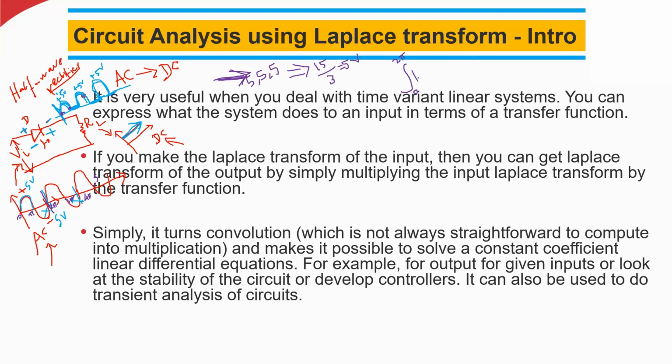So this one is Vm sine omega t dt. Sine is representing the sinusoidal waveform. Vm is representing this 5 volt. That is the magnitude of the input signal. So if I use this formula and solve this, then I can get the system response. I mean the half wave rectifier response here. That is how we have to do the mathematical analysis.